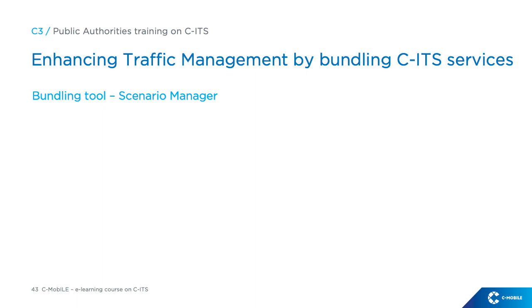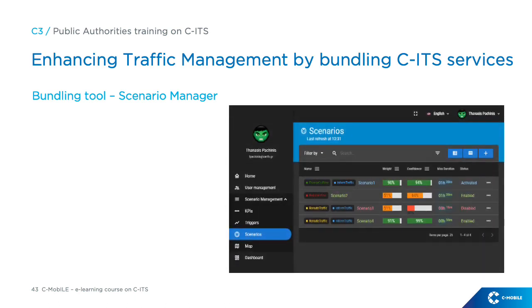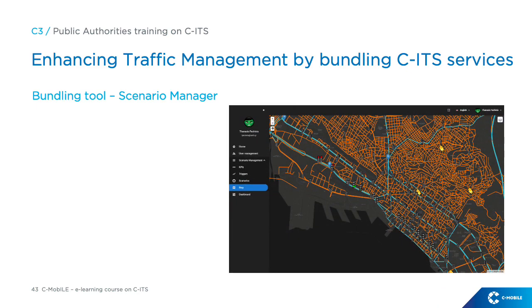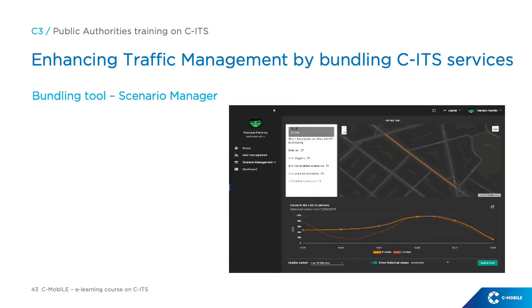The coordinated provision of CITS services can allow enhancing the traffic management, thanks to a bundling tool developed for road operators and traffic managers. This tool is made of two components. The first one, called the Scenario Manager, allows setting threshold and target values for each traffic control strategy, real-time monitoring of the road network and traffic status, and selecting, activating, or deactivating a number of control strategy settings and the associated CITS services.